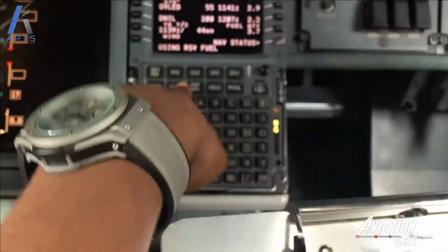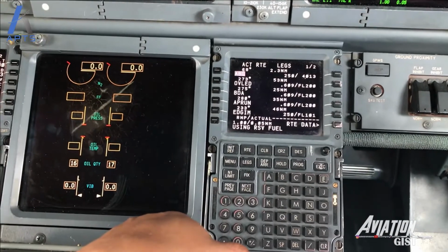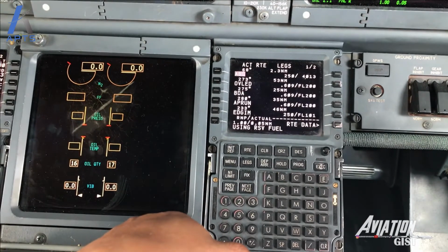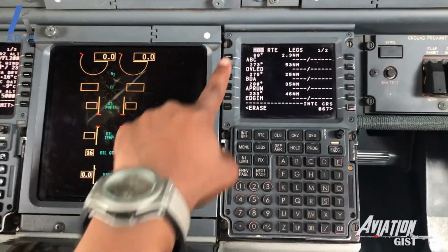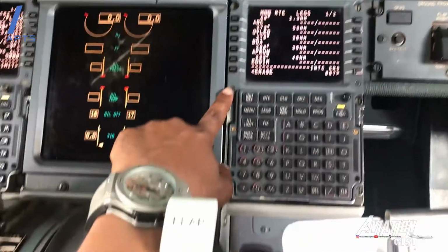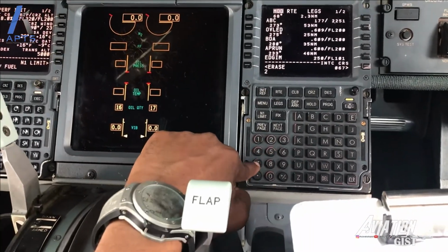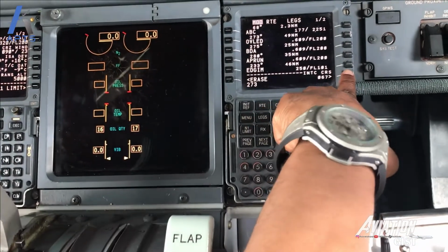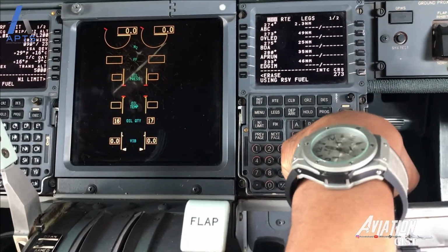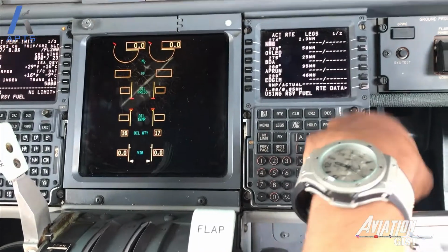Click on the Legs button to access the Legs page. Here, you verify each point matches that on the OFP under the route brief, then, if you are not departing on an SID, you can double-select the L1 key then enter the on-course track for the on-course waypoint. In this case it's the second waypoint on the legs page with a track of 273 degrees. Enter this into the R6 line select area and execute the modification.